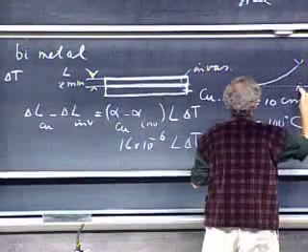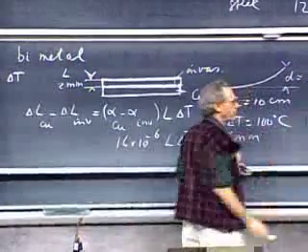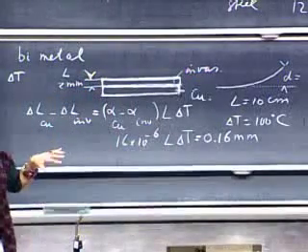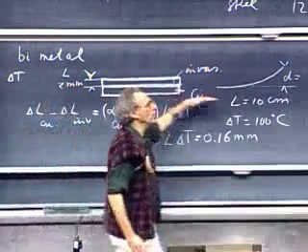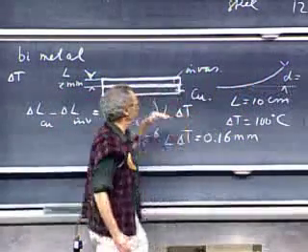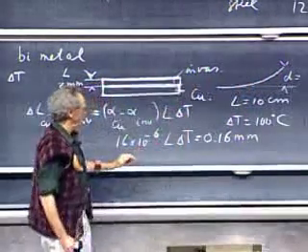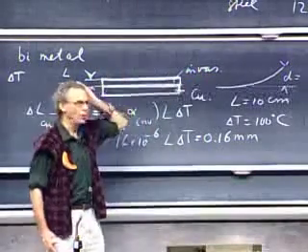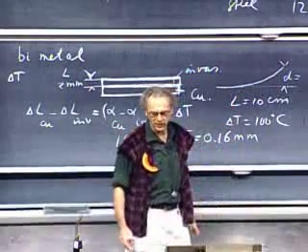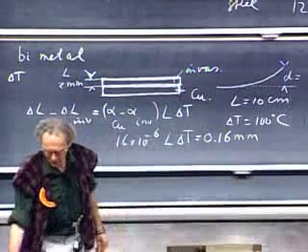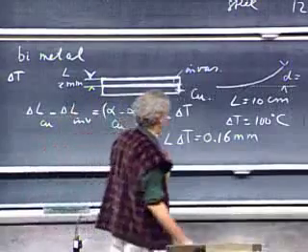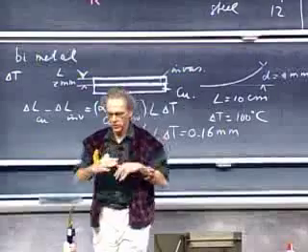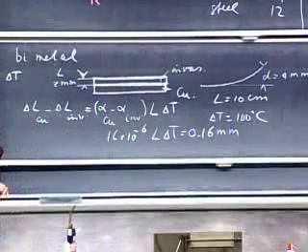substantially. For those of you who are mathematically oriented, I would advise you to make an attempt to calculate that. So you assume that it is a perfect circle. That's a reasonable approximation. And so you have an outer circle, which is longer by 0.16 millimeters than the inner one. And you try to solve and find what that d is. And I went through that exercise, and you want to do that too, perhaps, and I found that it's 4 millimeters, which for these dimensions is substantial.